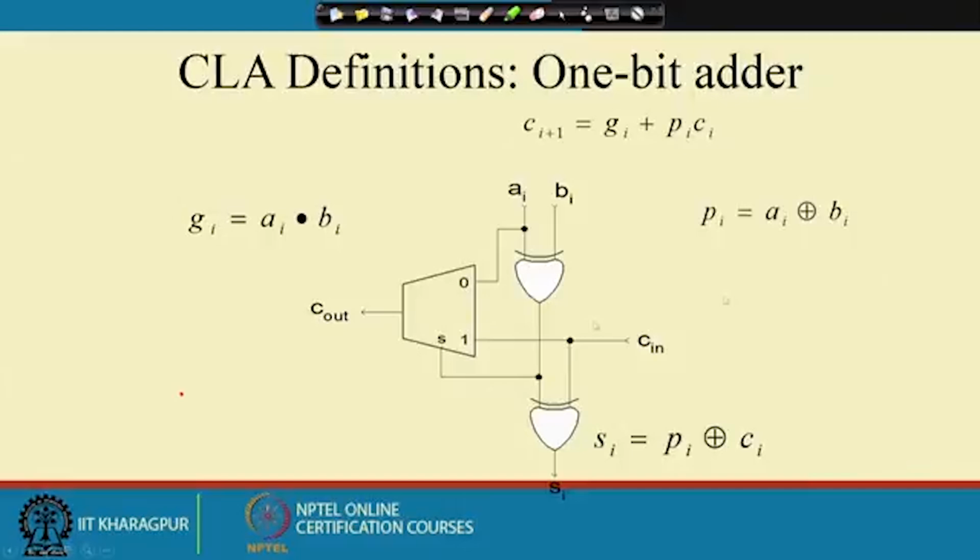So, using a mux I can easily skip: whenever the propagate value is 0, it will select either A or B, and whenever this value is 1, it will select the corresponding carry in bit, after considering the operation table of the full adder cell that we have seen.